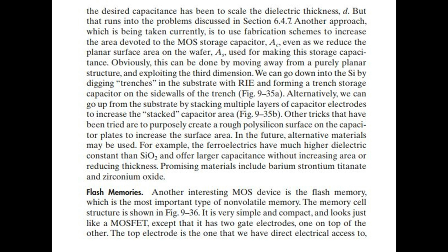In the future, alternative materials may be used. For example, the ferroelectrics have much higher dielectric constant than silicon dioxide and offer larger capacitance without increasing area or reducing thickness. Promising materials include barium strontium titanate and zirconium oxide.